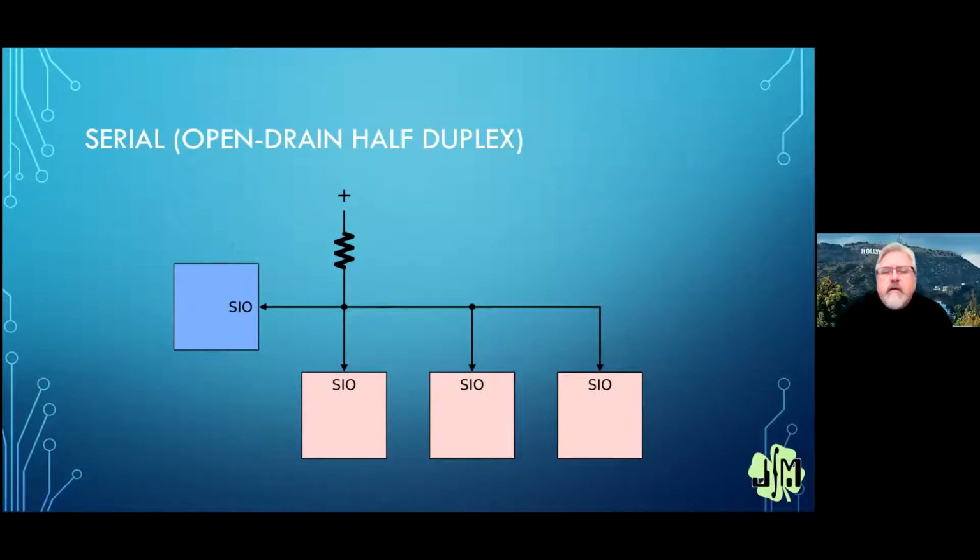So oftentimes in the simple stuff that I do, I will have a message address where 0 is considered a global message, so everybody responds to it. And then 1 and higher is an individual device address. And back in the golf course industry, when we were doing networked control systems, we also had group addresses. So we could say, okay, everybody on the back 9 shut down, or everybody on the front 9 shut down. We had group addressing that way. So again, that has nothing really to do with serial data or the mechanism. This is the protocol, which is how we're sending information over our serial scheme.